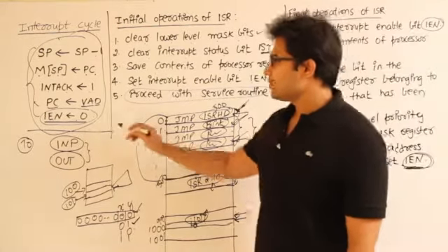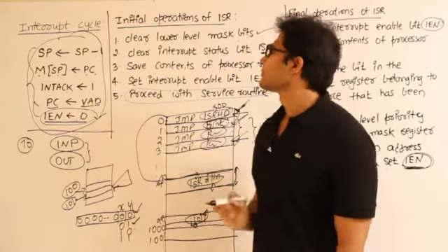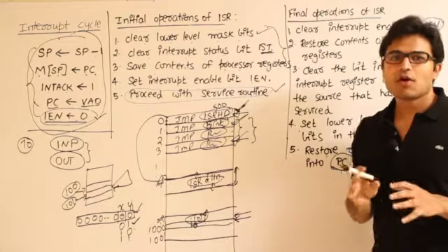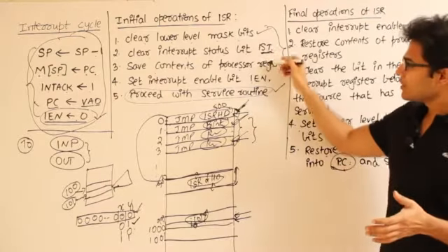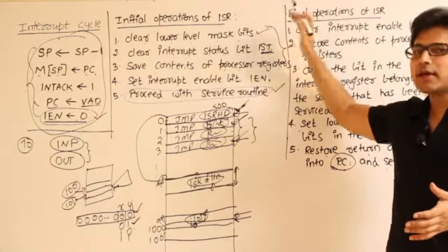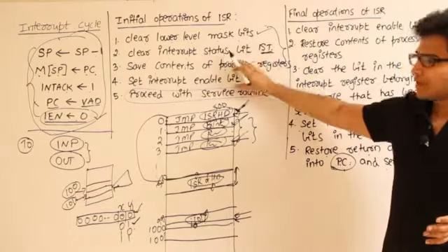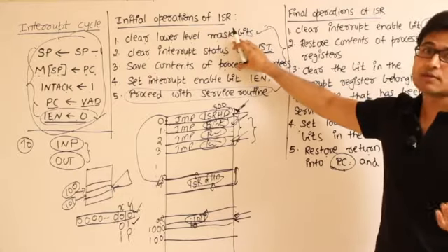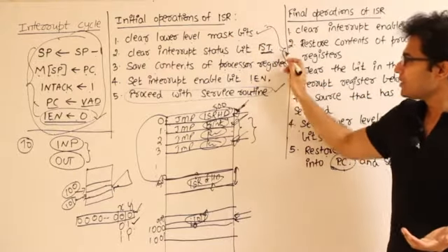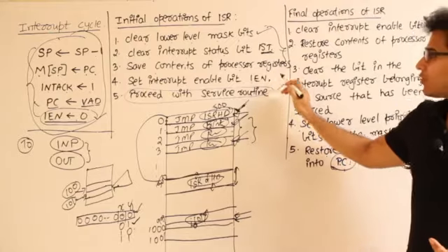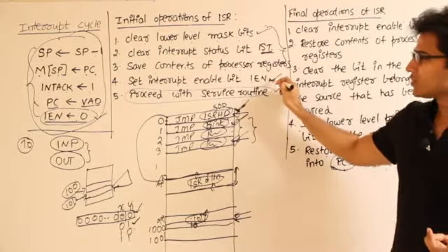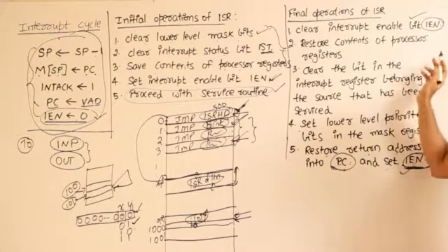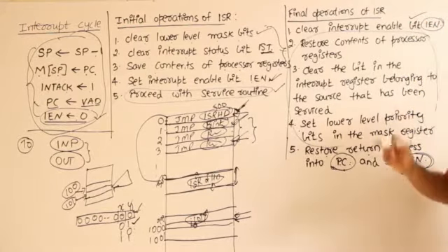If you observe, at the end of the interrupt cycle, we have disabled the interrupts and we are doing certain actions, and during these actions we don't want to be interrupted, because if you get interrupted in between and go to some other interrupt handling, this will lead to ambiguity, which means there's a chance that this particular request will be lost. That is why till you perform these actions, we disable the interrupts and set them again only after. Similarly here also we are disabling it and enabling it again. So all these things have to be done as a single unit.